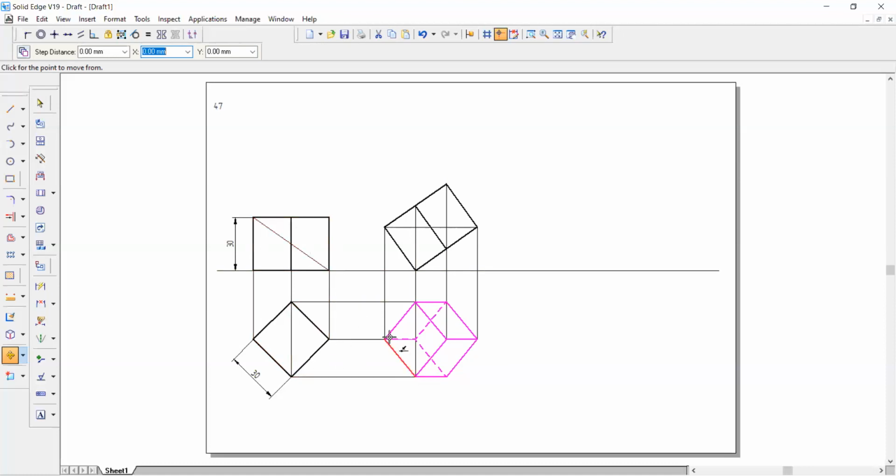In this case, A becomes this particular point here, and this particular point becomes your C1. So this is your solid diagonal here. Let me draw one line here, or it is not needed if you remember this. Just to show this projection line, you draw one more line here. Select the whole thing. He says it is perpendicular to VP, so go for move copy.